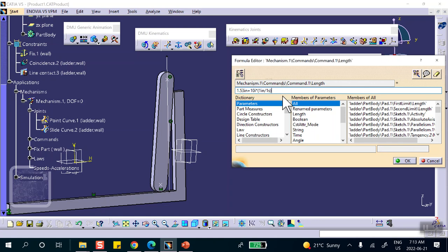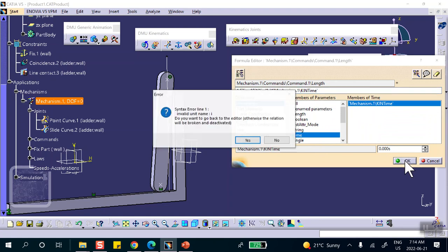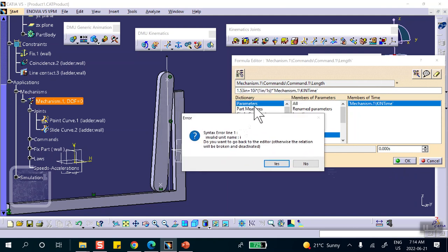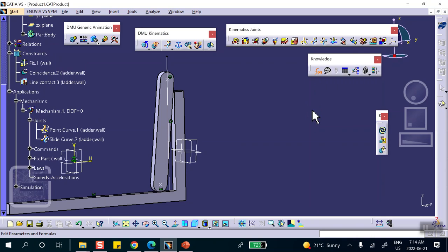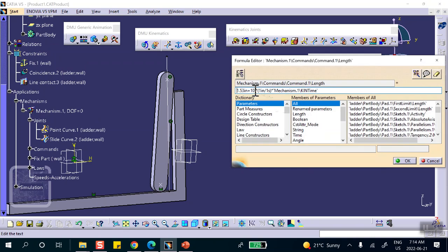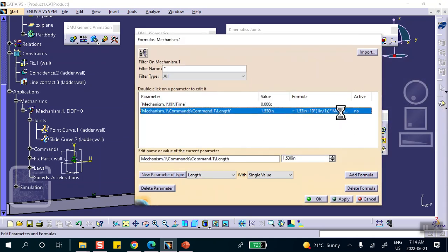We can try it. And then times time. Time is right here. Double click on it, it puts it right there. And if there are syntax errors, we're going to get it up right here. It says they're not homogeneous. Oh, I forgot this. Let's try it again. Let's double click on this. I had an extra I here. That's what it's saying. So this is times 10 times, not 10 I times. So you just leave it there. And no errors.